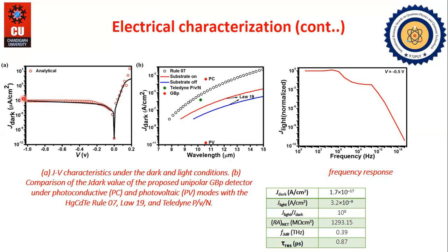This barrier layer will allow the photogenerated minority carriers to flow to the electrode while the majority carriers, dark current density, surface current density, tunneling current density, and re-injected light current density are filtered. Moreover, the shorter carrier transport path with bilayer graphene as a contact layer in the proposed detector would considerably reduce the recombination probability of the photoexcited carriers in the superlattice structure.